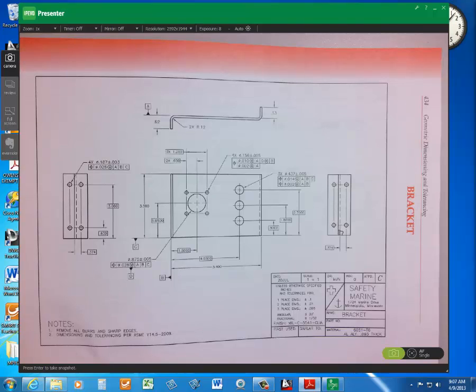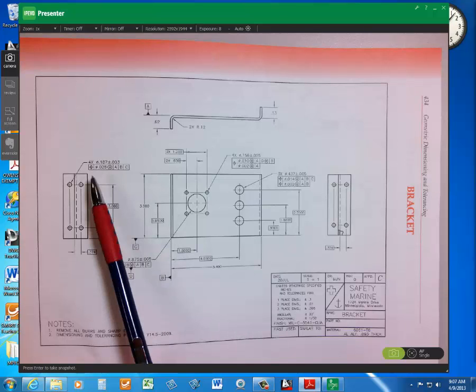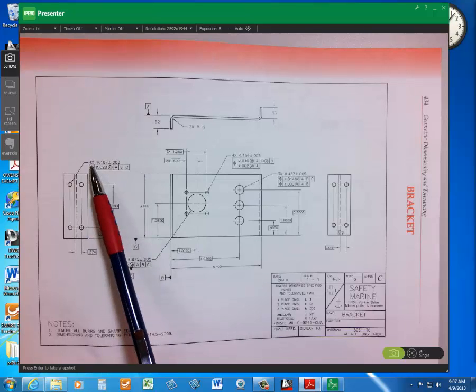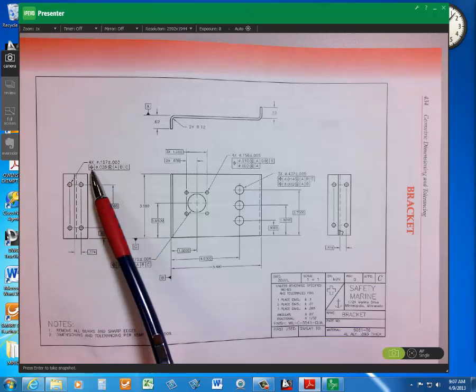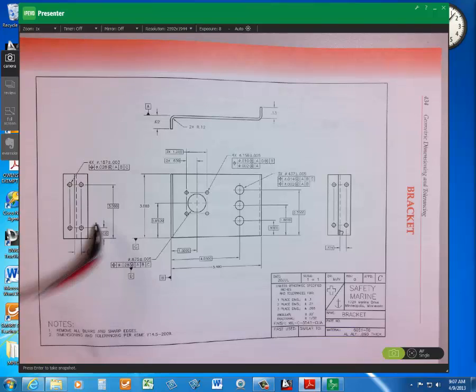And the multiple choice question there: which of the following most closely describes the positional tolerance? It's a single composite pattern. You've got 4 holes. See, it says 4 times. And there's a positional tolerance applied to the whole pattern,